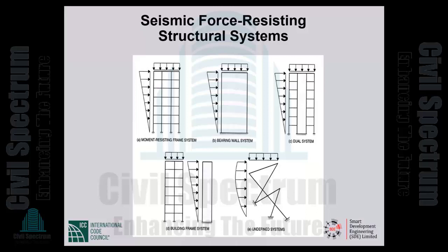In addition, you have to design the frames independently of the shear walls to carry 1/4 of the design lateral forces. This is the concept of the backup frame that has been with us since the 1971 San Fernando earthquake.